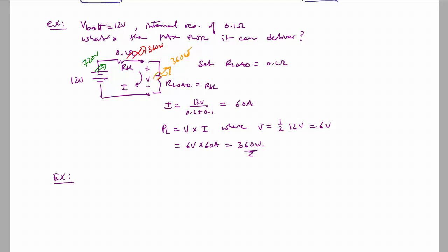Then the best thing that you can do to increase the power that's deliverable to a load is not to pick the load resistance to a particular value, but first it would be to set the Thevenin resistance to actually be 0, right?